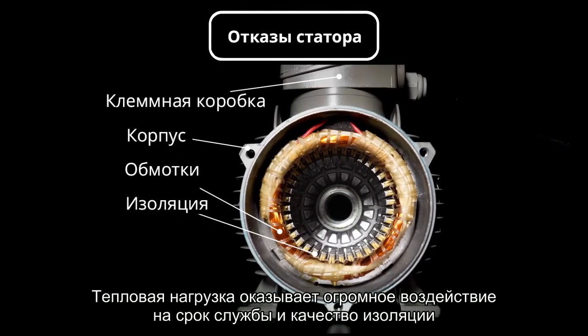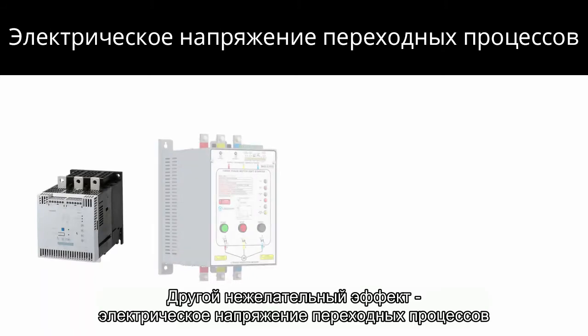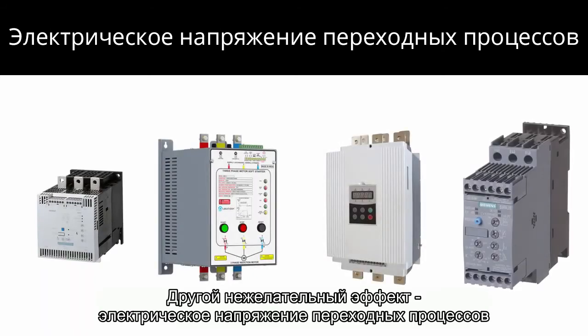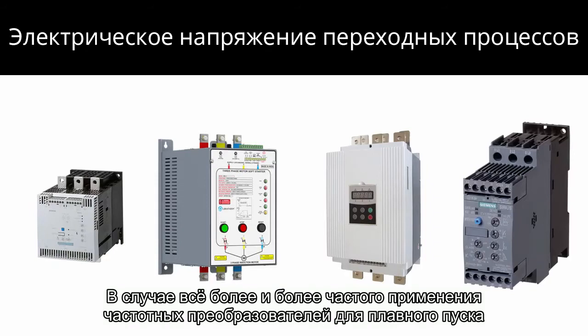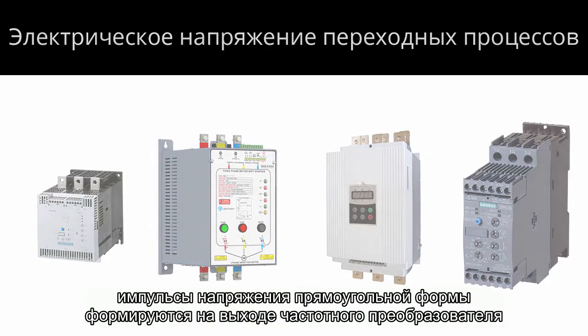Thermal stress has the greatest impact on the life and quality of insulation. Another undesirable effect is the electrical stress of the transient voltage. In the case of more and more frequent use of inverters for soft start, rectangular voltage pulses are modulated at the output of the inverter.